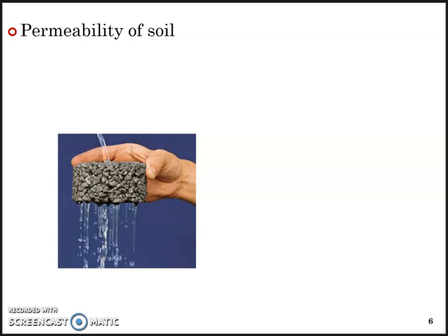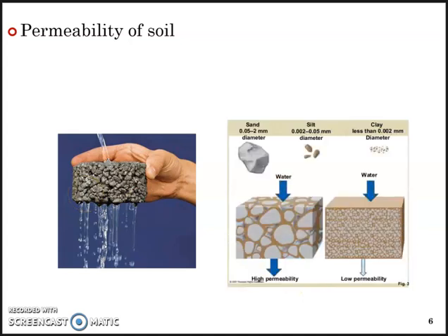Now, once you understand the 3-phase system diagram, the flow goes to the permeability of soil. Soil as a material is permeable. So permeability of soil is the property with which it allows water or any fluid in general to pass through it. This figure shows concrete as a material being permeable. Likewise, soil again is permeable. And in this module of permeability of soil, you'll have to deal with the Darcy's law, based on which you have a few derivations and a few relations. So in short, permeability of soil is based on Darcy's law's definition in its very crude and basic format, but you have got different other theories as well.